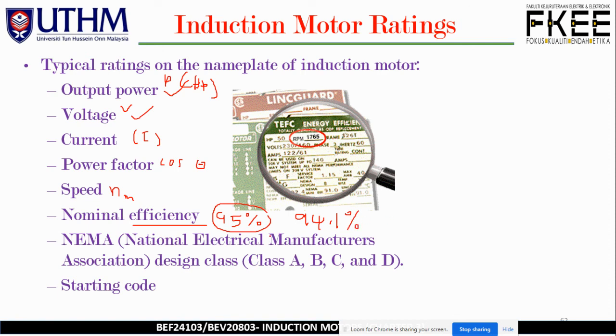And then this is what I mentioned earlier, NEMA, the National Electrical Manufacturers Association. The design class falls between class A, B, C, and D, and also the starting code letter F I mentioned earlier, in order to calculate the inrush or starting current.